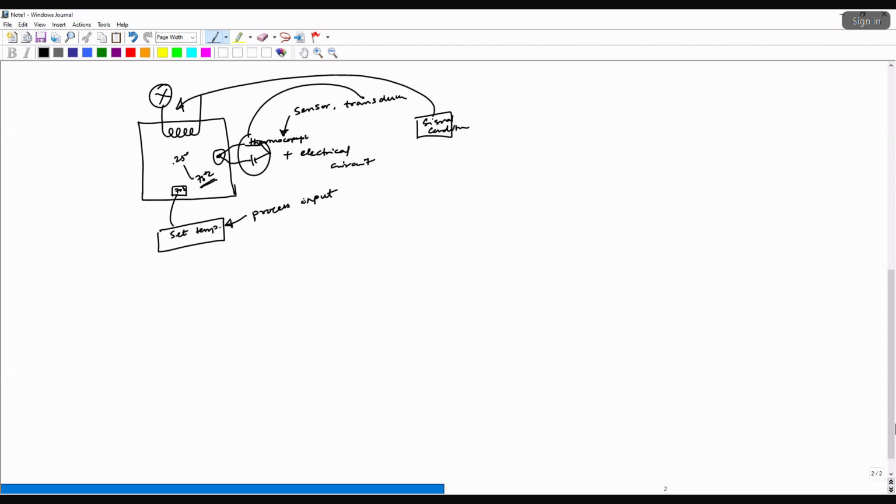And so the heater is cut off. So from 75 it goes to let's say 68, and then it comes back to 72, and finally it reaches 70, right? So this is a very simple measurement system where we have the sensor, transducer, control signal stage, and also you have the feedback stage.